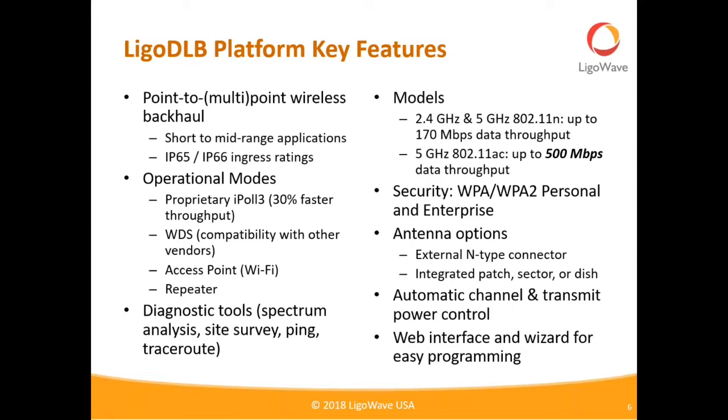who have integrated us with other vendors, which I normally do not recommend, but occasionally there's a need for that, and so we are backwards compatible so that if you need to install us in an environment where you have existing equipment and you're just swapping out individual units, we can run in a backwards compatible mode that will let us talk to other vendors' equipment using the WDS standard. There is special firmware that you could put on these if you wanted to run these as an access point, and you could also run these as a repeater.